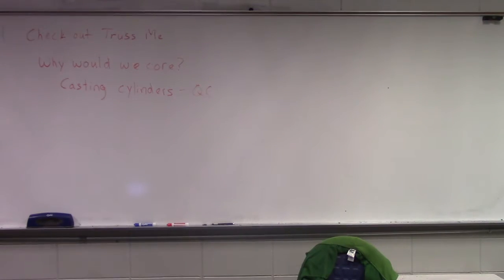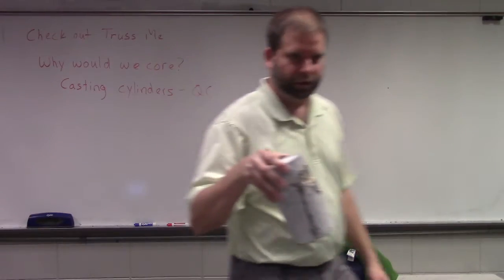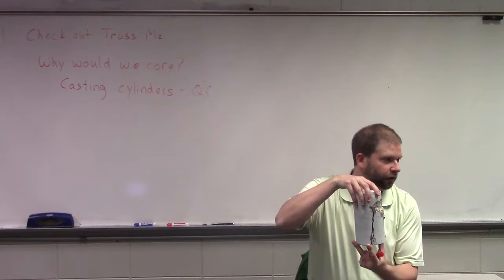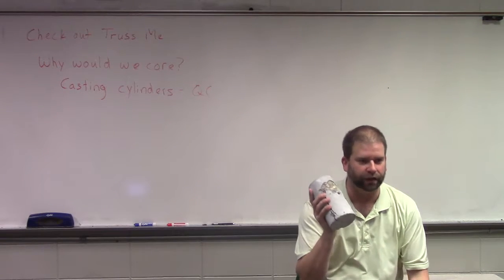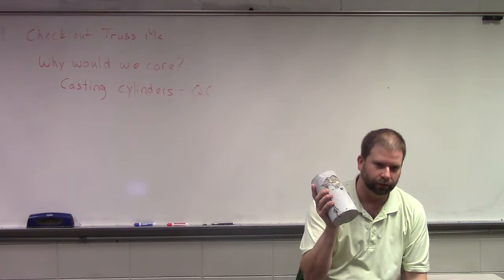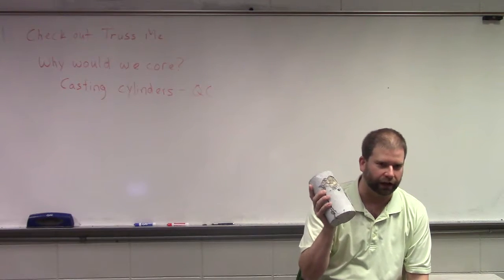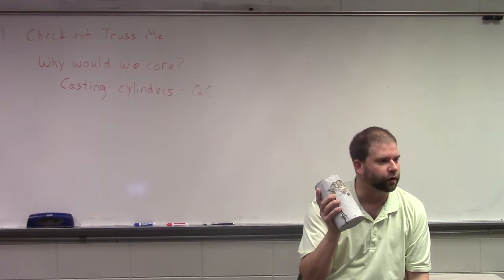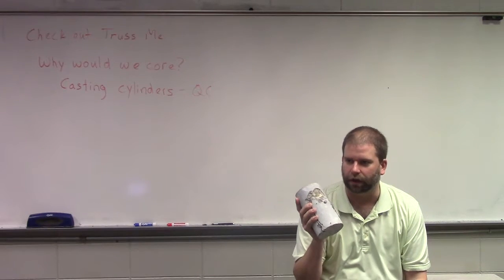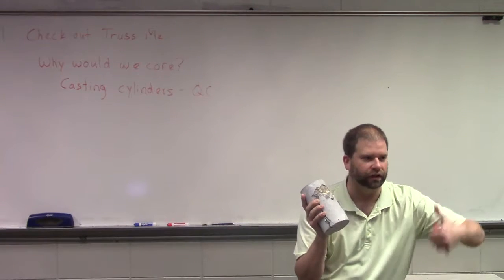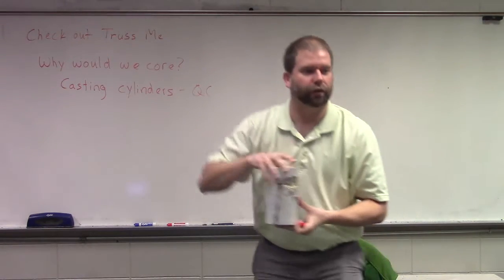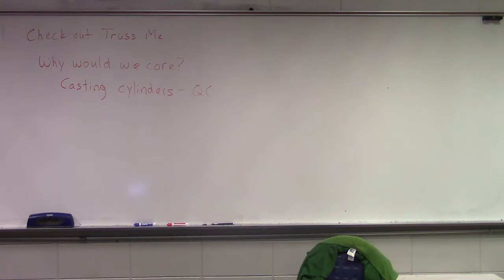So typically speaking, we're not making 6-inch by 12-inch cylinders anymore. We're making 4-inch diameter by 8-inch length cylinders, okay? Now think about the concrete that's out on the job site. Are they similar at all in size? No. Not even close, right? So what happens to concrete as it's curing? It starts increasing in heat. As it increases in heat, it increases the rate that the cement hydrates, so it drives the strength gain.